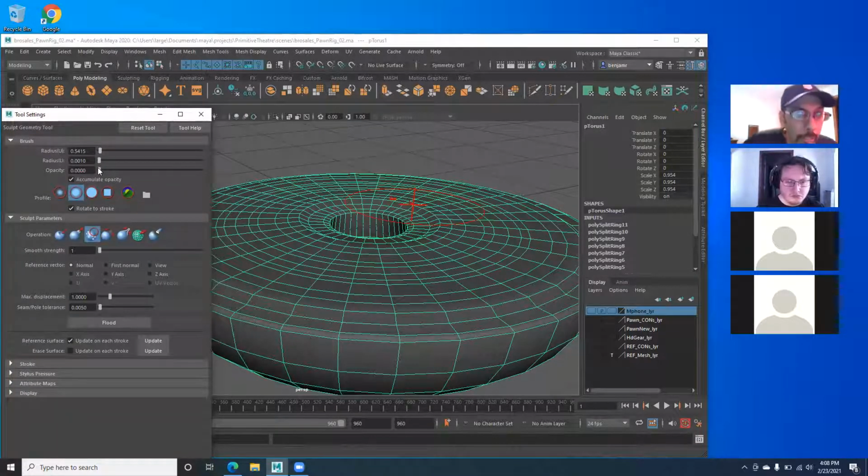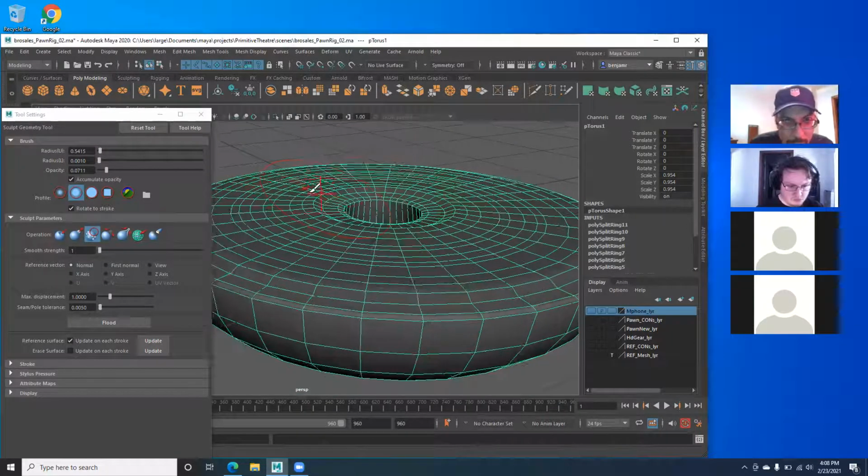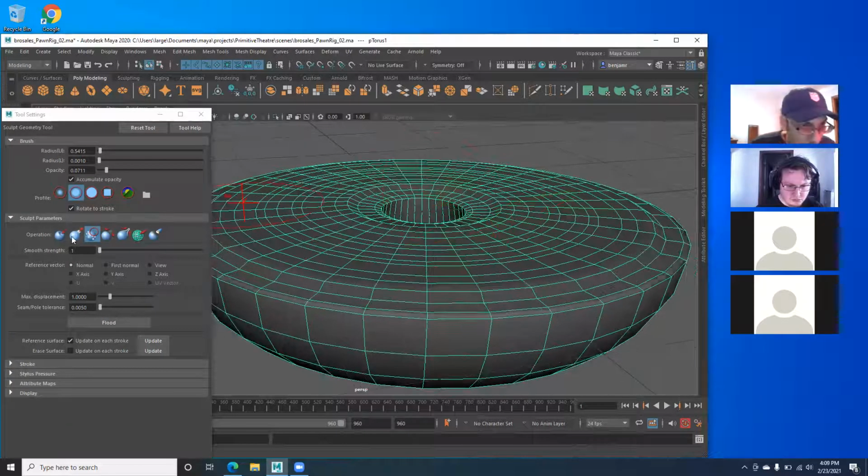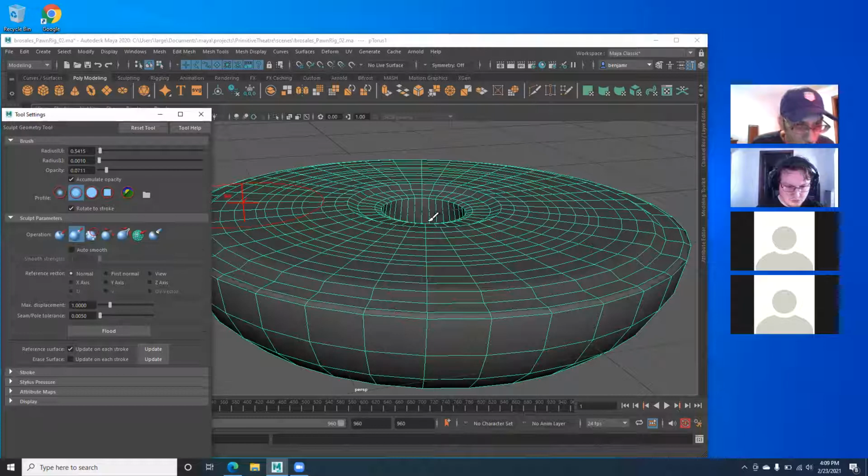And when I say way down, usually like 0.004 or, you know, really small is good. Sometimes I say way down and my students only go to like 0.1. You can go even further. You want to test it first and see if that's good enough or too far. So I'm going to use the pull tool and make my brush smaller.